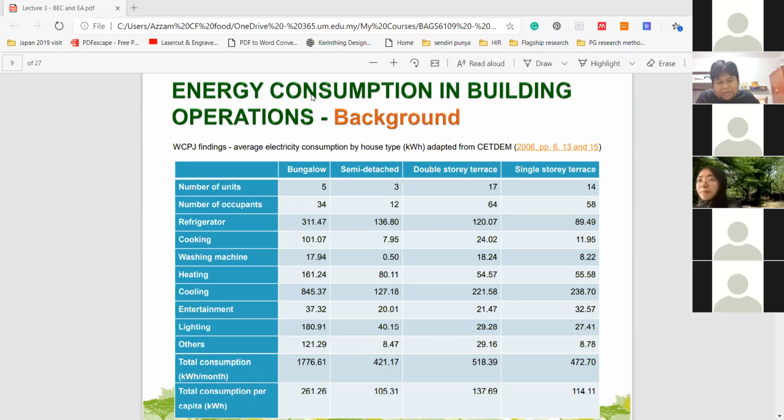Which is a bit strange because if you look at it logically, okay, terrace houses normally will only have two external walls, one facing the front, the other at the back of the house. These two facades have windows and openings and doors and whatnot, those are the only two facades. And they also have a couple of shared walls, okay? So you don't get daylight illumination onto the walls, so you don't get heat coming in from there. And coincidentally, you also don't get any heat coming in from the other house,